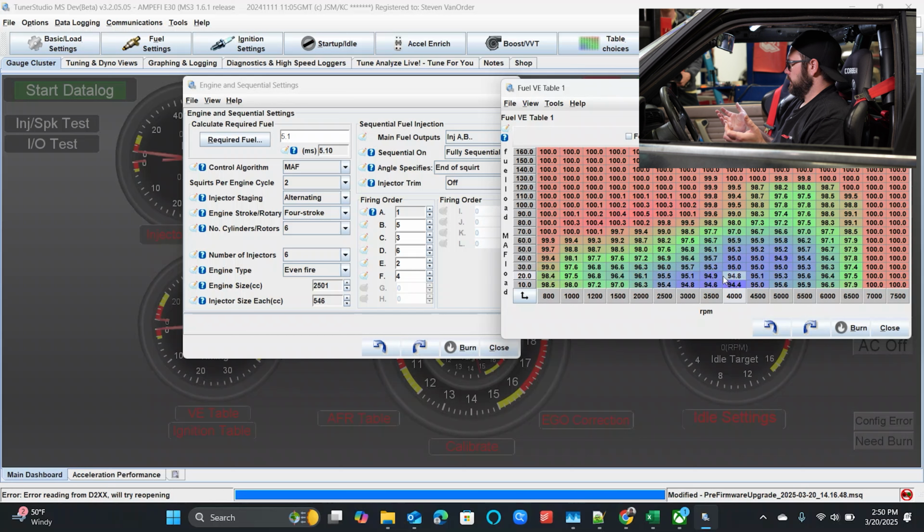Why? Well, can you fill the cylinder more than 100%? An engine like a Coyote, that's possible. Race motors with very aggressive camshafts, or specific engine setups with efficient cylinder heads, efficient camshaft design, exhaust, in certain parts of the RPM range where scavenging is happening, it is very possible to fill the cylinder more than 100%.